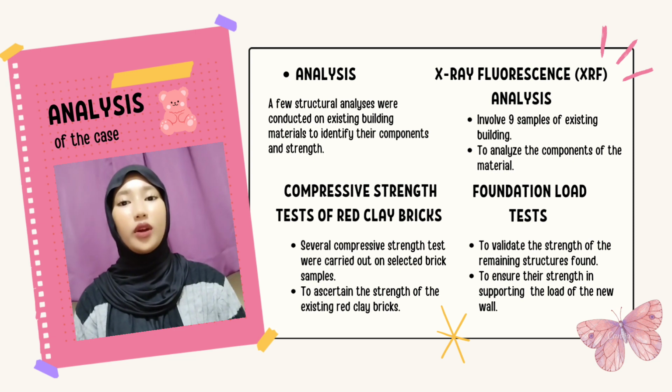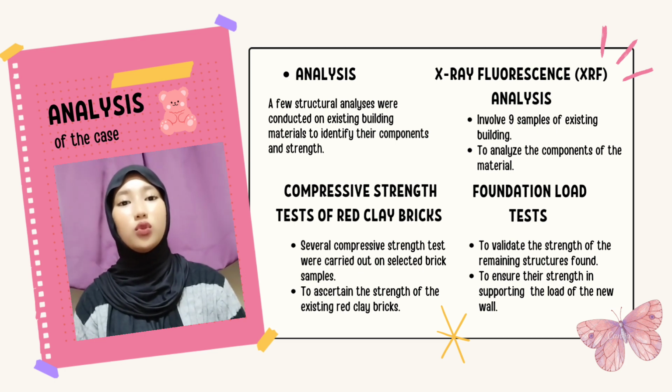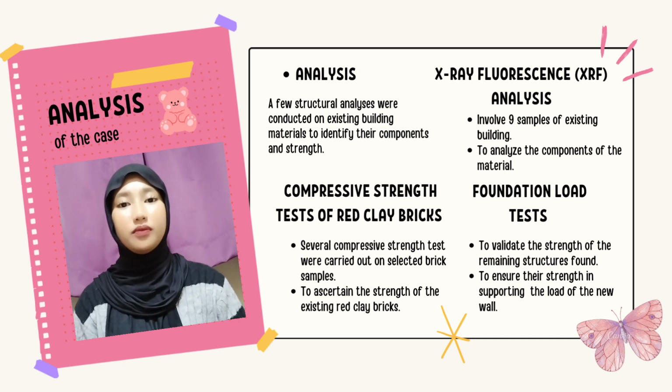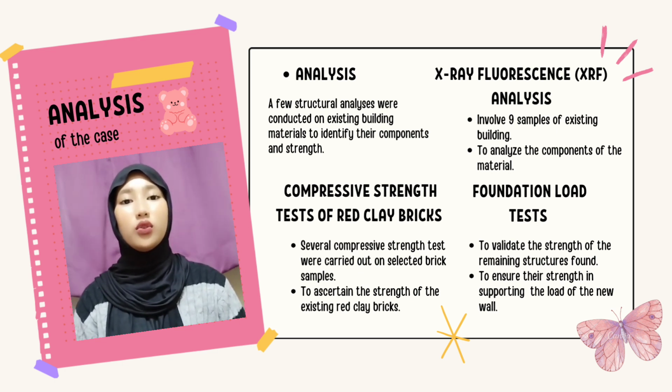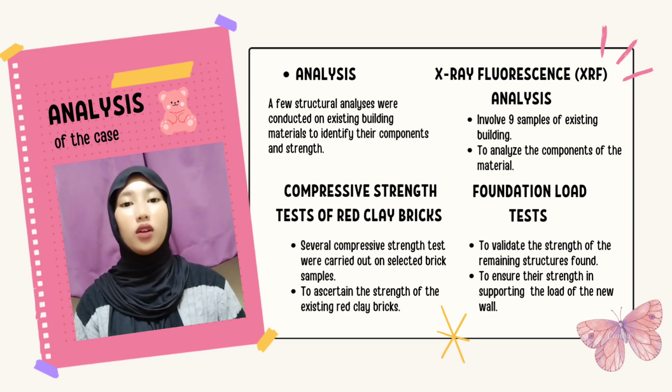6 different points of load testing were identified along the existing wall foundation to ensure their strength in supporting the load of the wall. The true load and bearing capacity was derived from the loading of the existing wall by measuring the area of the wall and the block self-weight.